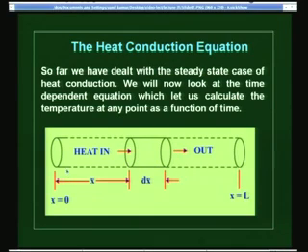Okay, so that problem would lead to an equation of the form which I just wrote. So we are not looking at steady state here, we are looking at this long thin rod. We assume it to be thin so that across the cross section the temperature is uniform, and it is insulated all along its length. So the heat enters here and goes out here.